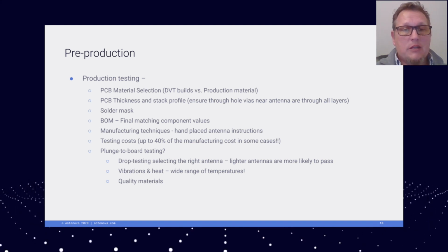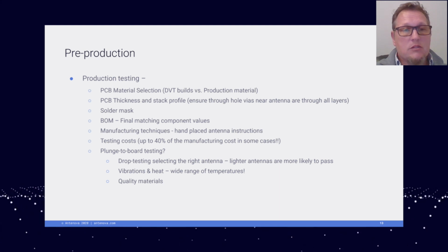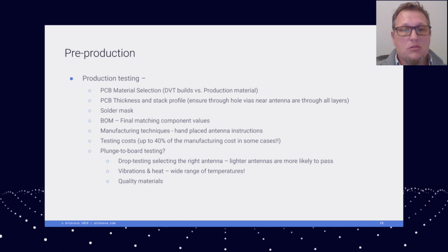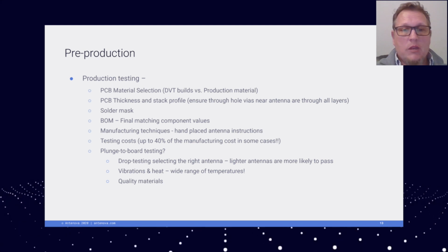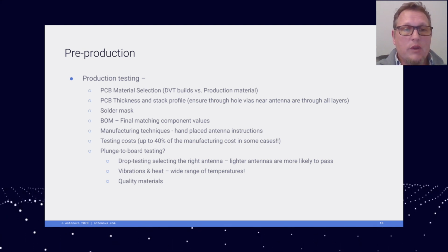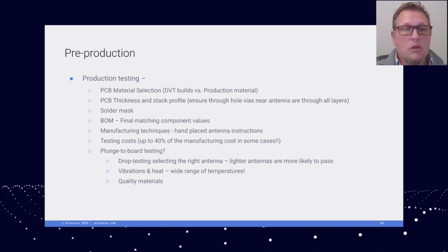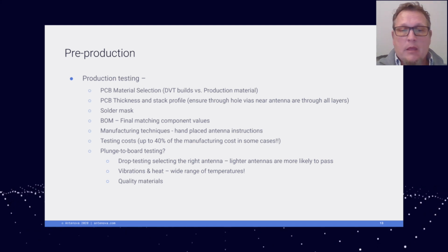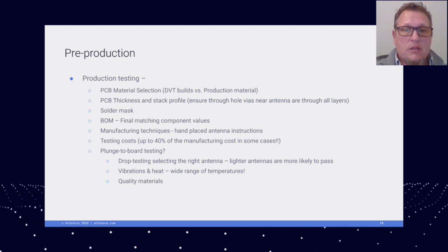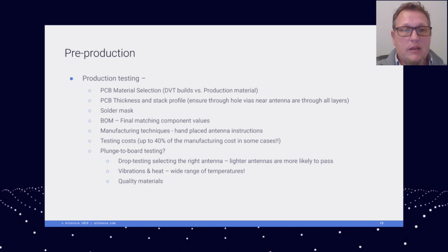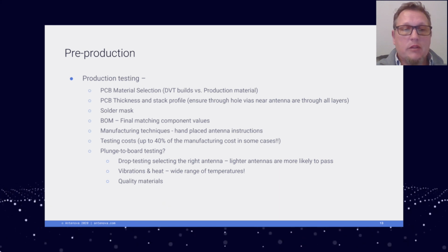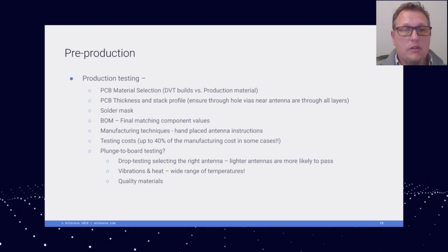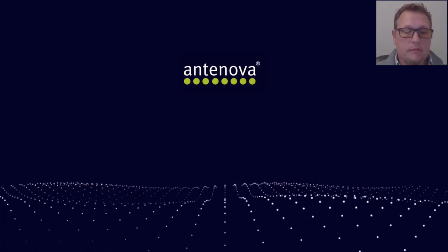Verifying that your antenna is connected to your board is significant. It's pretty important to make sure that the antenna is making connection to your radio. You want to make sure that there's some way, a test jig or whatnot, to try to ensure that the antenna is making connection. Also, during drop tests, you want a way to verify that the device is still working. Typically that's in a test jig, and you turn the transmitter on and make sure that the device is still transmitting.